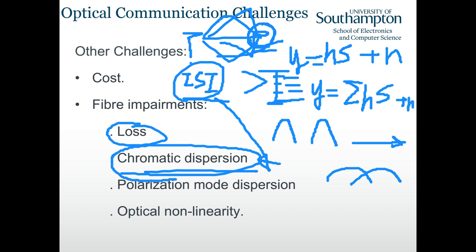So how do we mitigate inter-symbol interference in wireless communication? We mitigate this by using OFDM. This is because of the convolved product here. So this is like a convolved product between H and S. Convolved product in the time domain would be just a simple one-tap product in the frequency domain. That's why we use Fourier transform, and we modulate signals in the frequency domain so that we do not encounter the inter-symbol interference in the time domain. Okay.